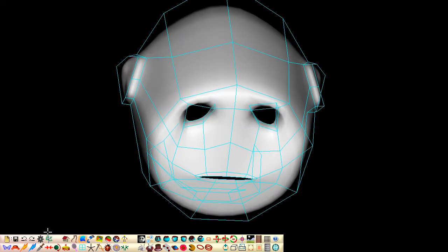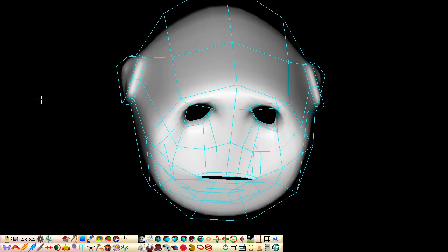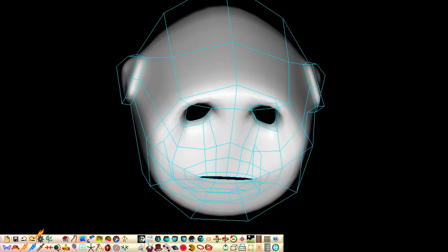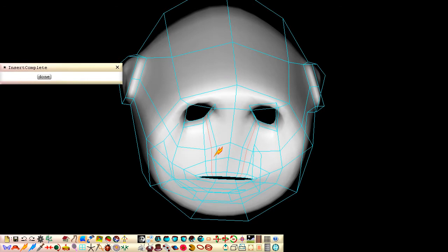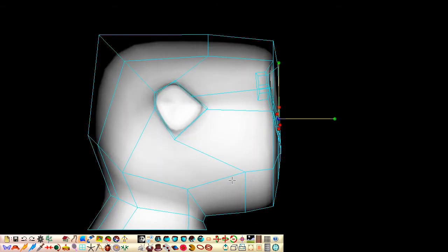We want another set of lines going from the eyes to the mouth. And a ring inserted around the mouth. Now we can add a line going from the eye here and divert it so it goes back to the other eye. Note we diverted this time where we had a four-sided polygon in the control cage. This resulted in the creation of non-four-sided polygons, but we'll use this result to our advantage in forming the structure of the nose. Now we have the key lines for our nose, we can drag out some points to form the nose.